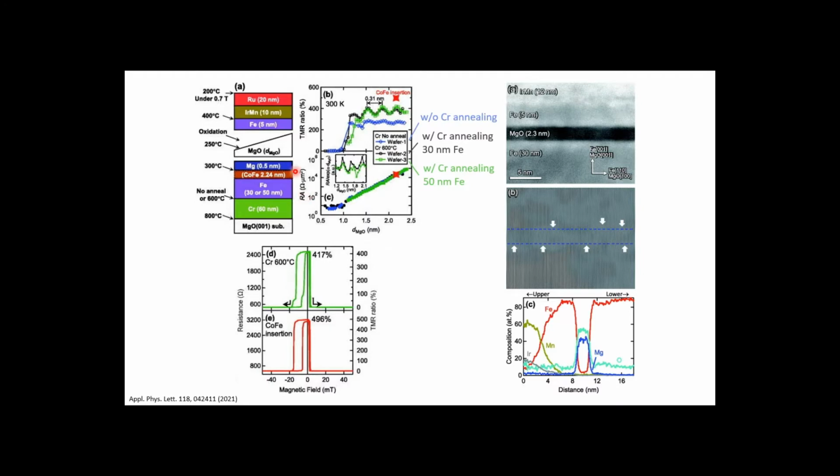So in this work, the tuning of the interface states was conducted with magnetron sputtering, electron beam evaporation, post-annealing, and also natural oxidation. So firstly, we can see the schematic MTJ stacking structure. Here, we can see the different processing parameters and the layer structure.